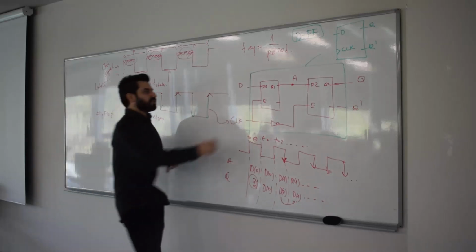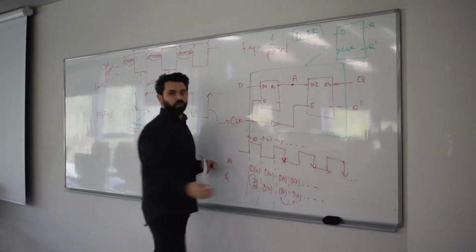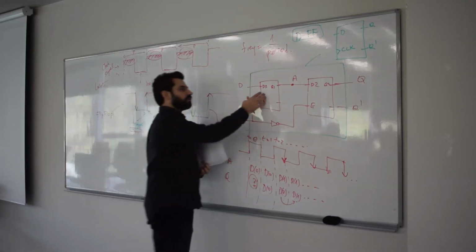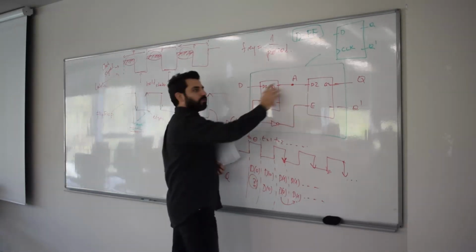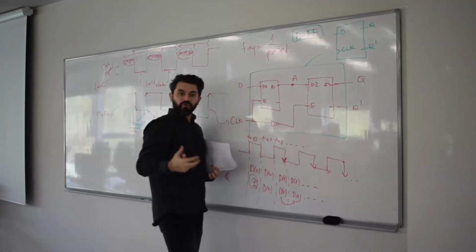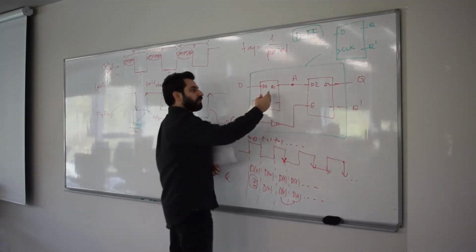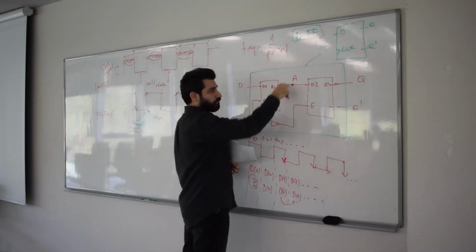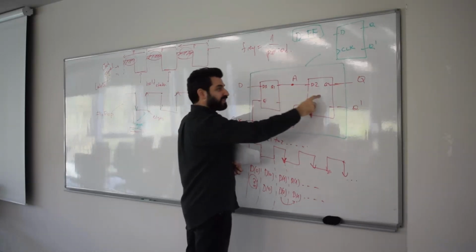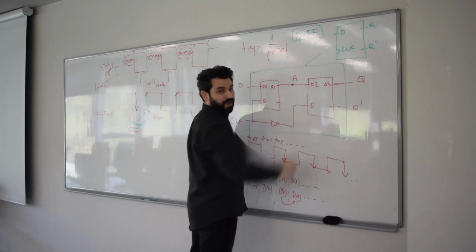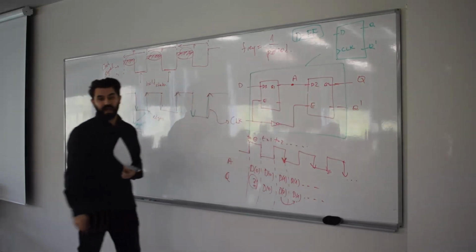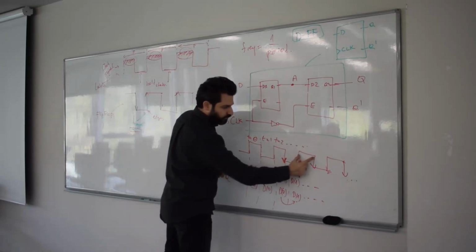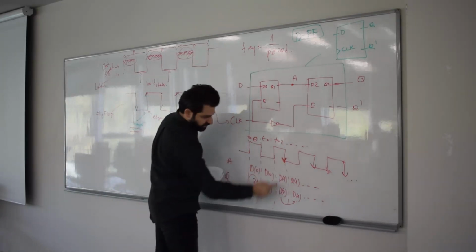Okay? Because these two D latches work in alternating fashion. One is enabled, the other disabled, then this is disabled, this is enabled. And the way that they work actually cancels out the noise, because this can be copied here. The noisy version could be here. But since this is disabled, that noise is not passing through the second D latch. That's why we don't have, for a specific certain time, for example here, changes cannot happen.